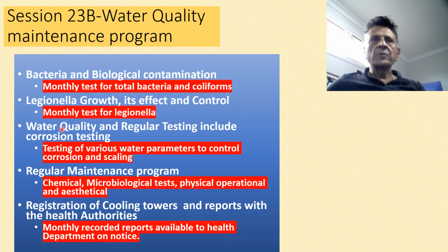For the sake of proper maintenance and operations of the cooling tower, we also need to ensure the water quality with respect to corrosion. So we have to put in corrosion coupons to check that water is not in a corrosive state.